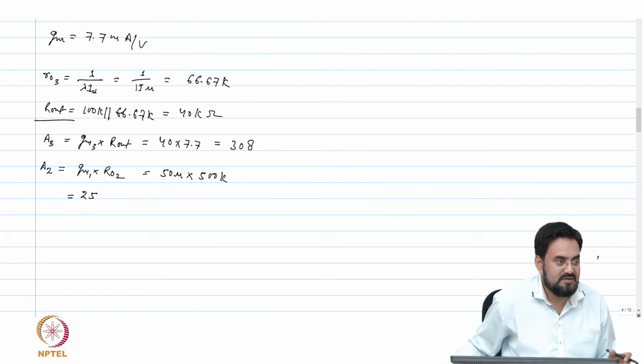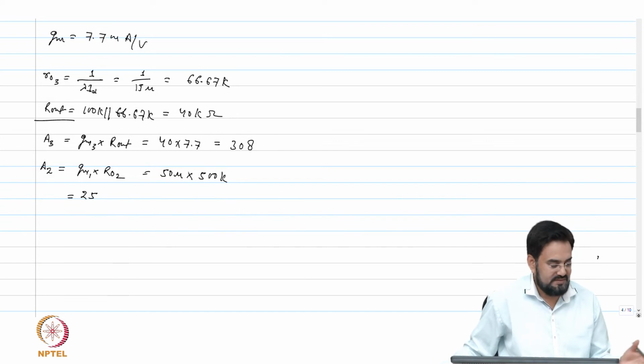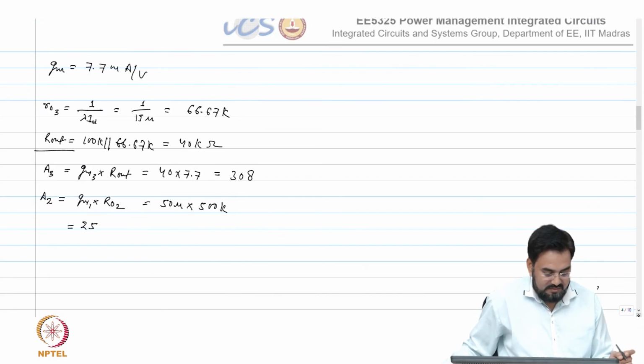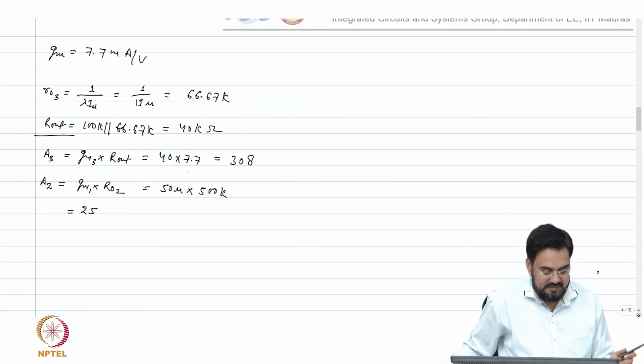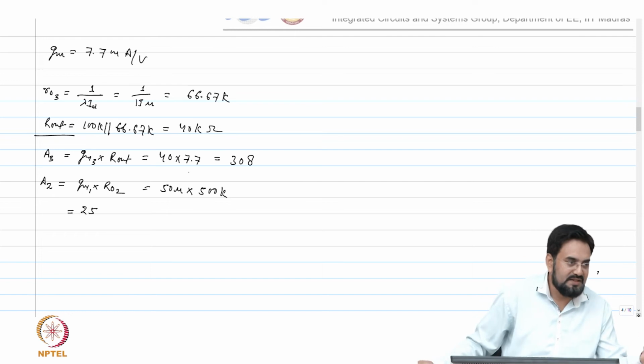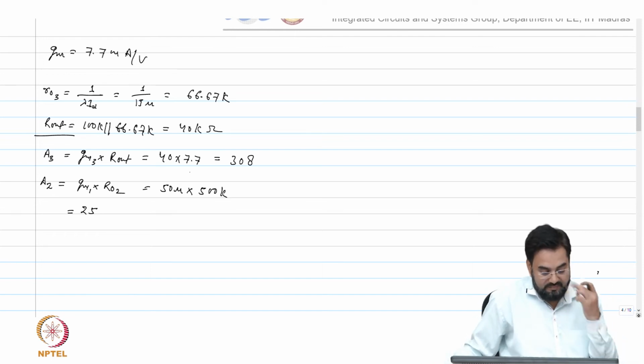Close to 70 dB or what? 77.7. 77, closer to 80 dB. And if you calculate at 10 milliamp or so, it may drop by maybe 20 dB or so. So 57 dB. And I think we assumed 60 dB. That was a rough assumption, but it will be less than that actually.